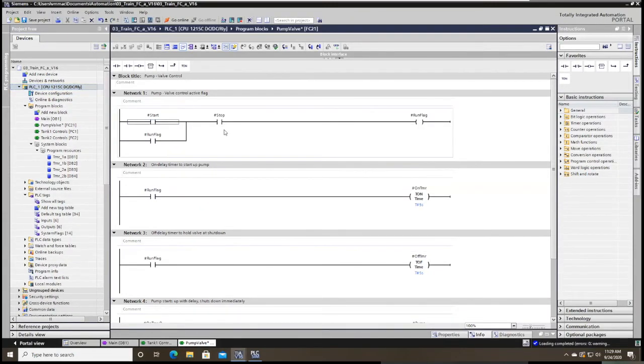So an e-stop typically, physically, has contacts that are normally closed. So even though this is a normally open contact here, because the e-stop's not pressed and the contacts aren't open, this will be closed in the program because the actual physical contacts are closed. So we'll pretend this is closed as if the e-stop wasn't pressed. When you click start,